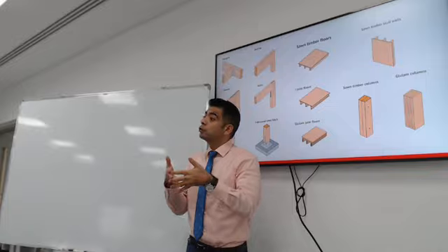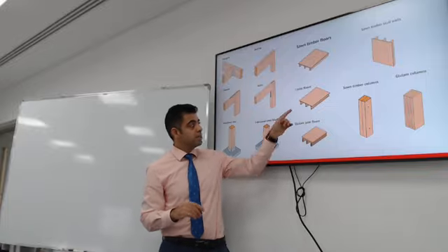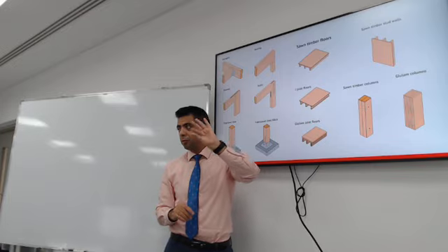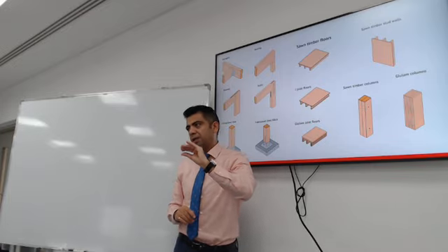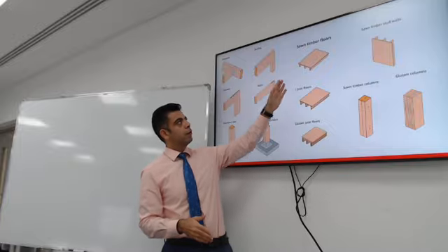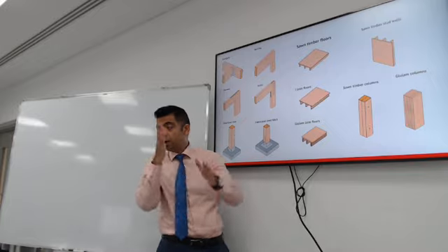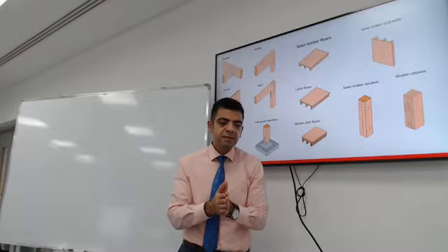And what is going to transfer that load? The plywood. Do you see the thickness of the plywood? Usually it's not very thick, and that's why it's not going to span far. So you look at a floor system like this, you can make it from Glulam, you can make it from sawn timber, the standard sections.